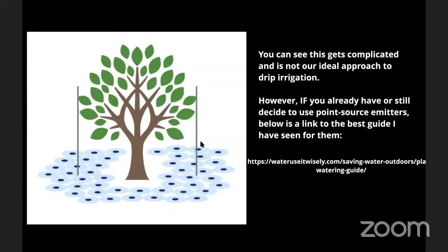And especially if you're dealing with trees or larger shrubs in areas like in Southern California, where we get the Santa Ana winds, if you only have a couple of little drippers near the base, that's where the root system is going to be trained to stay. And then when we get those winds, especially trees, they're going to be more likely to fall over than if we've been giving an even watering to the whole root zone with a drip grid system, which we'll look at next, to where the roots have been trained to go out, find water, and establish more in their natural pattern.